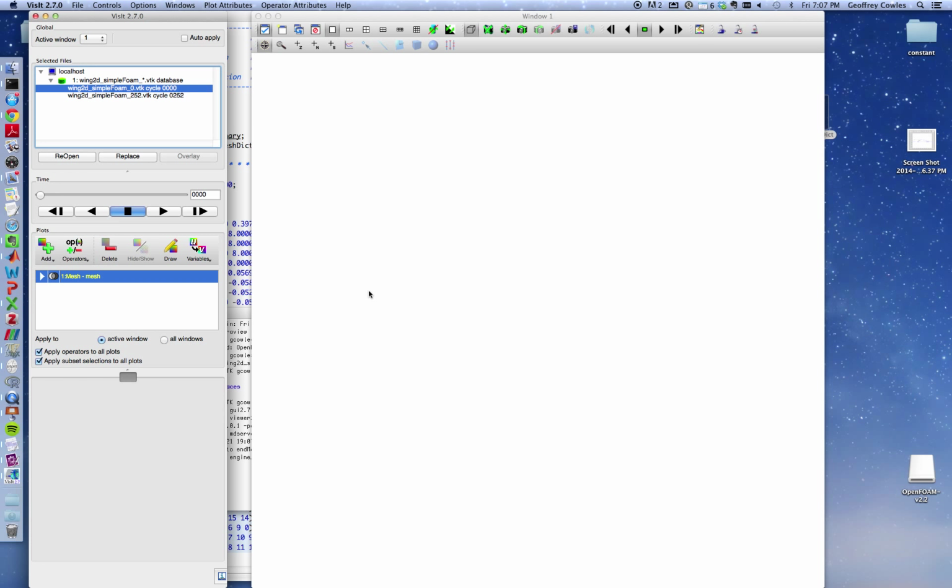So let me zoom it back out again. So you can see the domain is quite far in the far field, and that's to get far field and reflection effects away from the airfoil. So if you apply infinity conditions here, or free stream conditions, they are truly free stream conditions because they're not feeling the effect of the airfoil at this location. So the file you're creating in the Matlab script generates the information that OpenFOAM needs to generate this mesh, which we call a C grid.